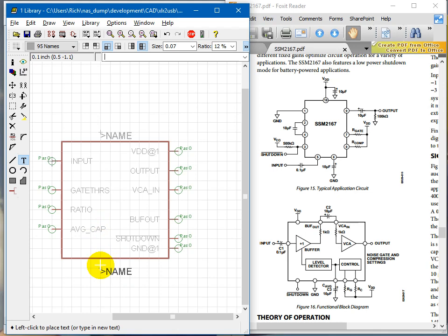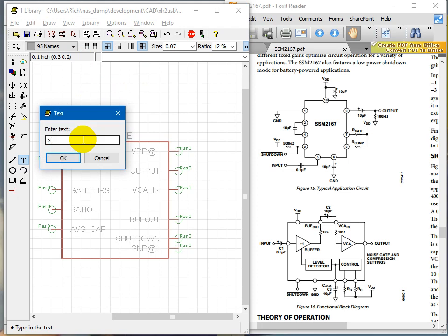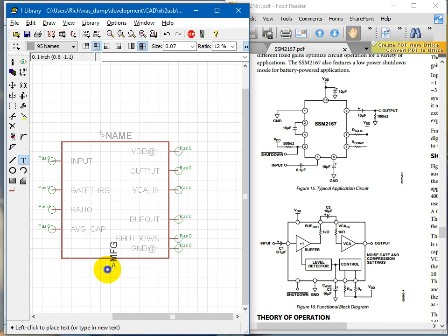All right, last, this is something that I like to do a lot because I'm big into organizing my information and helping myself out wherever I can. Every time I build a part, and we'll see this a little later, I create 4 or 5 extra macros or attributes that I can use. Name is not the only attribute or macro that I can use. I can use any attribute, including the custom ones. I will be creating a couple more custom ones on there. And one of them is called MFG for manufacturer. I usually put those at the bottom.